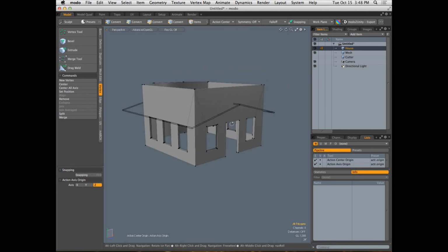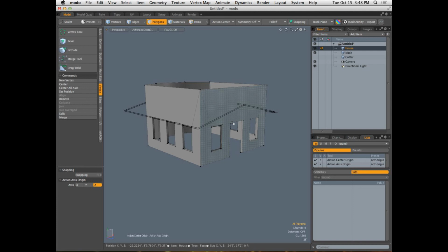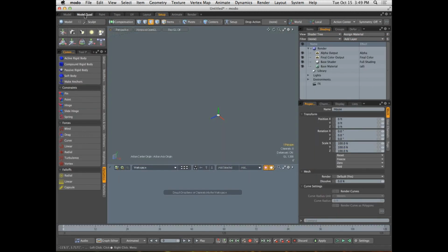Because now I'm going to use the roof line. This is why I put the roof in another mesh. Initially, I said I'm going to put the roof in another mesh just to ensure that I don't screw anything up. But I thought I had a couple steps. I'm going to use the roof as a Boolean for my walls. I'm going to slice the walls. And so I'm going to get a whole bunch of edge segments that define where the roof is. And then I'm going to delete all the polygons that I don't need. So, excuse me. Didn't mean to go into the Setup tab.